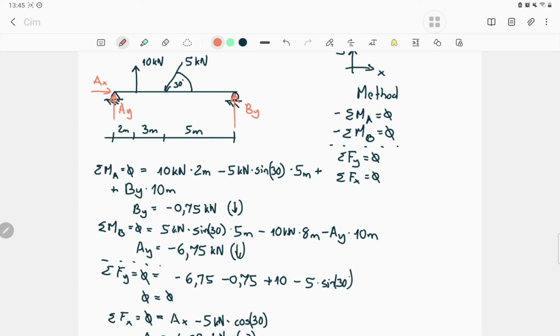For example, I choose a point exactly under the middle of the beam, with a vertical distance of 2 meters. It's my decision. This will be the P point. You can choose anywhere, just be sure it's not inside the beam, somewhere above or somewhere under the beam. Why? Because in this way, the moment equation will include the Ax too.